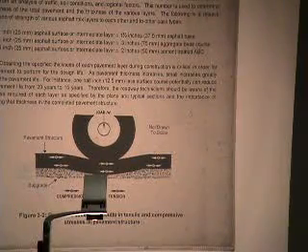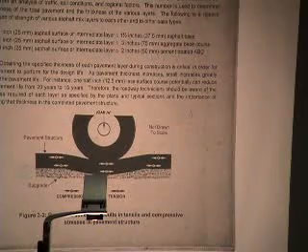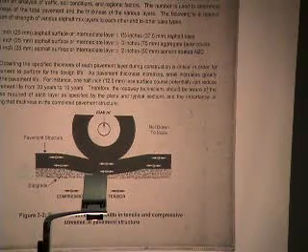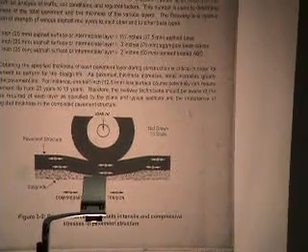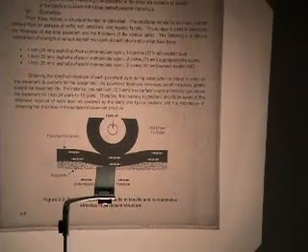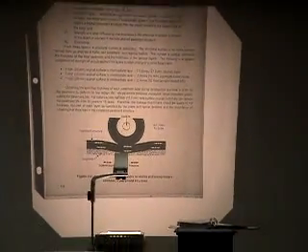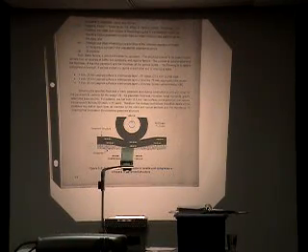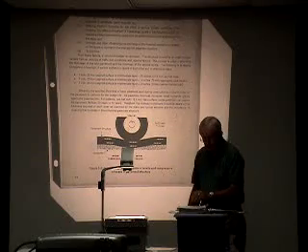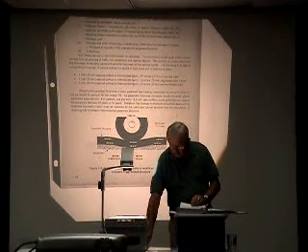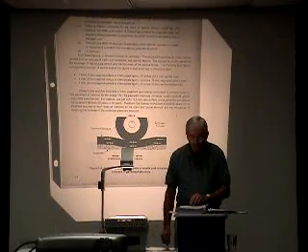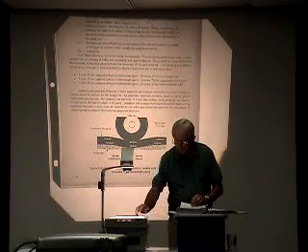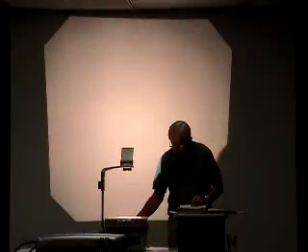The idea is to minimize that deflection, to the extent possible, such that it can undergo many passes of vehicle tires over it before the distress starts showing. But all these things considered, we came up with the Superpave mix types. These are listed there on page 3-3 in your manual.